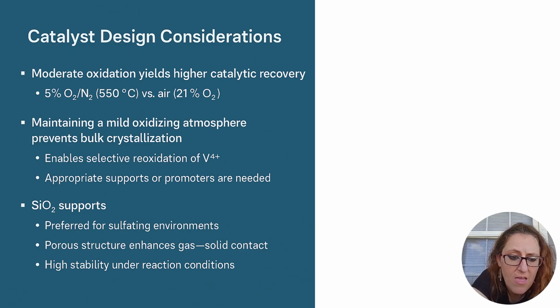Silica remains stable even under cyclic heating and cooling, ensuring long-term durability of the catalytic bed. Its high porosity and surface area provide an ideal matrix for dispersing vanadium species, promoting efficient sulfur dioxide oxidation, minimizing mass transfer limitations, and evenly distributing the reaction heat through the bed.